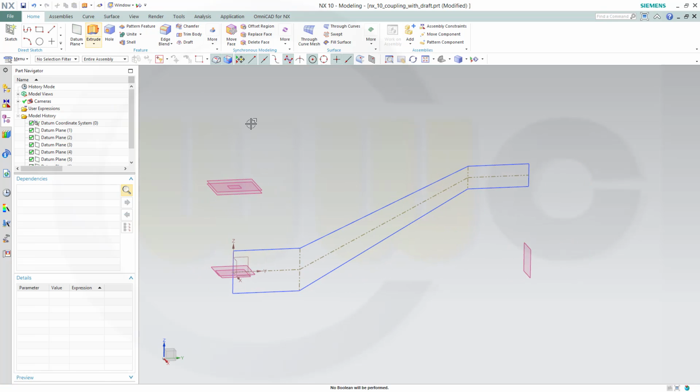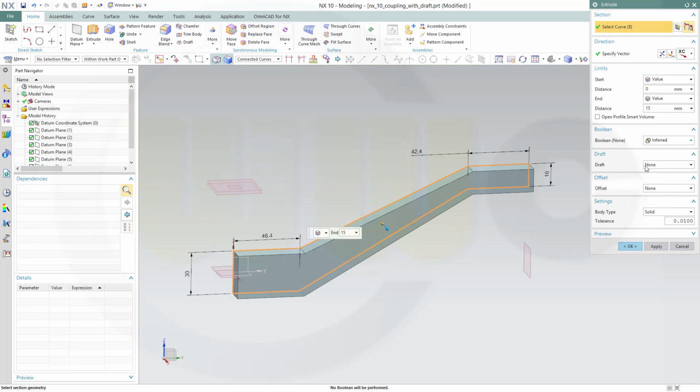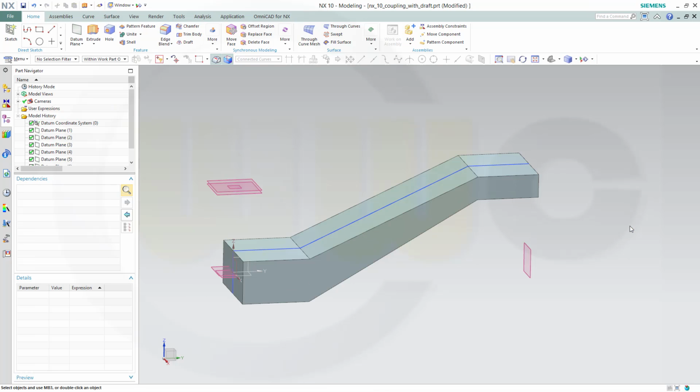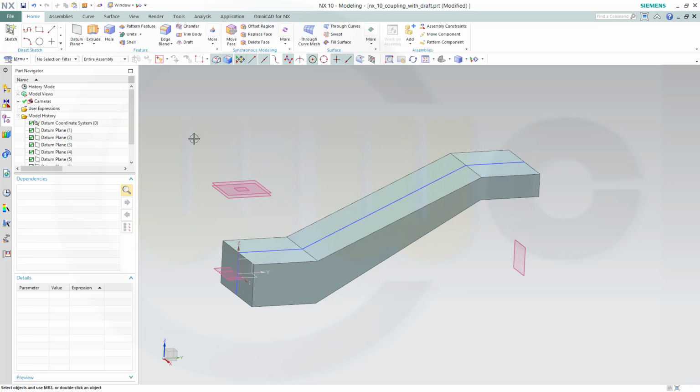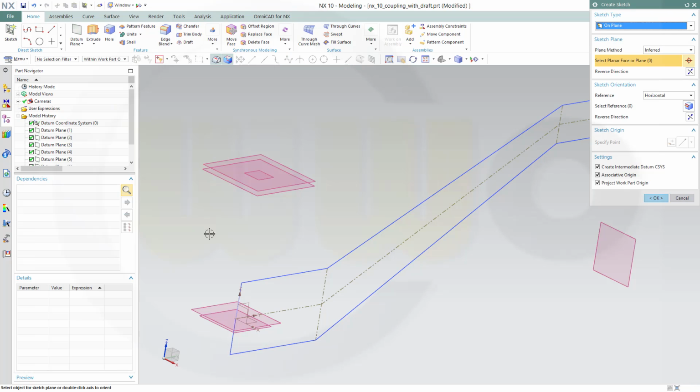Now you could make an extrude with that sketch, connected curves, that's okay. The direction would be XC, and it should be probably symmetric, and the dimension would be, let's say, 30 to both sides. And okay. Another sketch. I could hide that body, so switch to the bodies, just hide that body, and back to timestamp order, and another sketch on that plane.